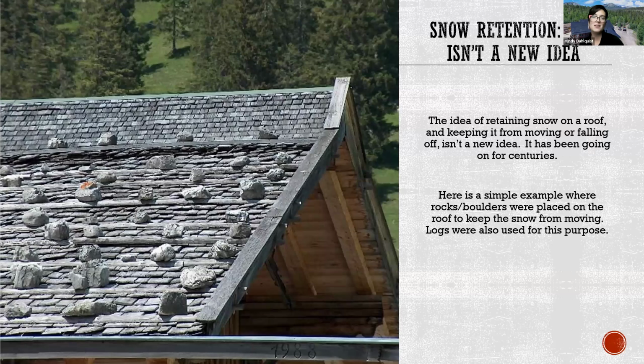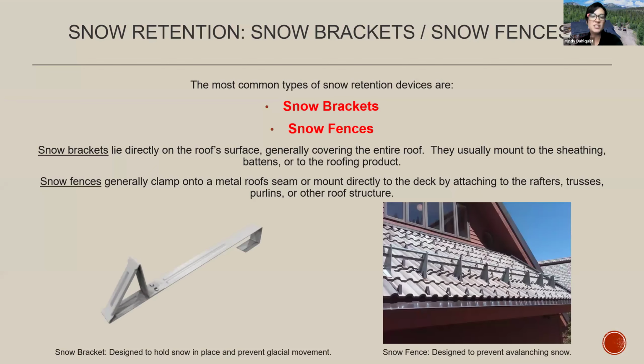This is something that has been going on for centuries. Oftentimes it was logs, rocks, or boulders that were put up on the roof to keep the snow from sliding off. Now we've moved into more modern devices, such as snow brackets. Snow brackets lie directly on the roof surface. Generally, they will cover the entirety of the roof, mounting to the sheathing, the battens, or the roofing product itself.